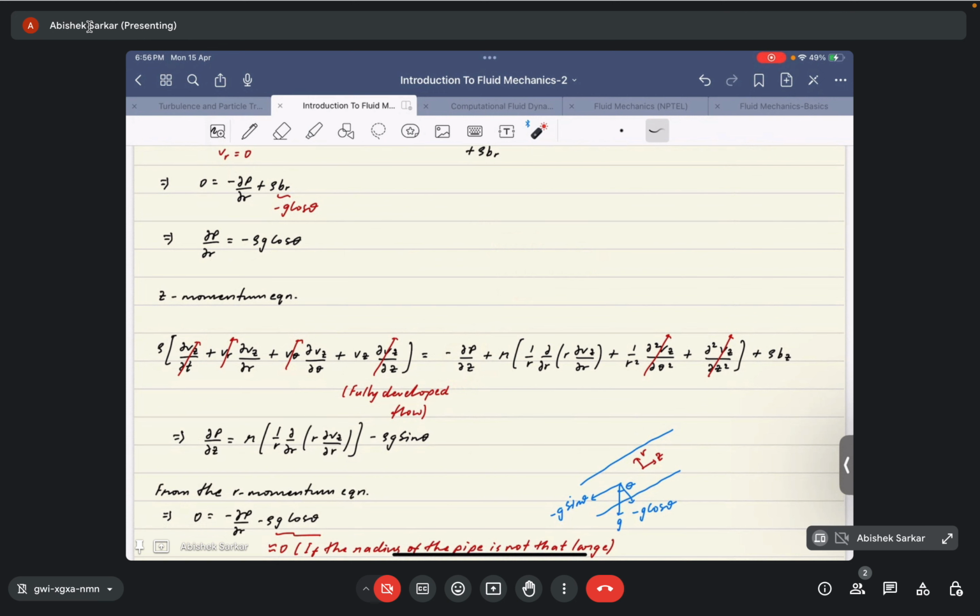Logically, this term has to be non-zero because the flow is along the z direction, and there has to be a pressure gradient along that direction to have a primary flow. Through mathematical rigor also it is not zero, because no assumption has been made yet that can nullify this term from the governing equation.